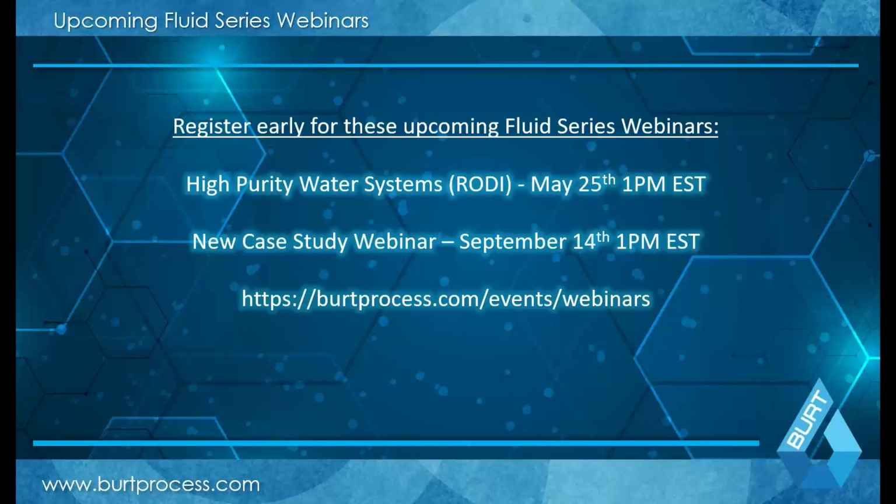One of the things you have to understand when you're talking about pH probes, and really for the treatment tank, if it's running by gravity, for example, you can have a certain level of particulates coming into the tank. You'll get some suspension of it, obviously, in the agitation. It'll flow out. If you have a lot of solids or debris coming into the tank, you do run the risk of it building up. You don't want to run the risk of it damaging your pH probes if it's in suspension, basically colliding with them.